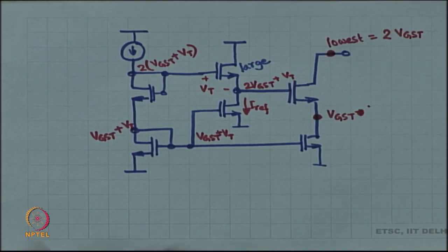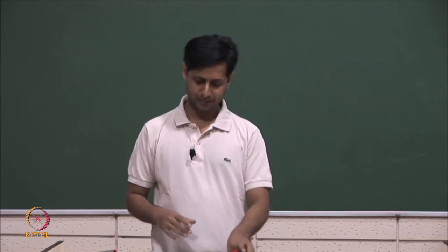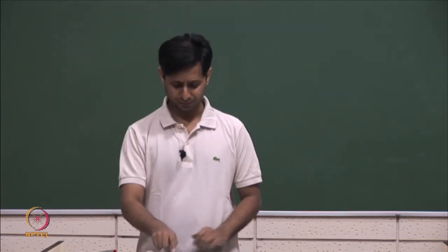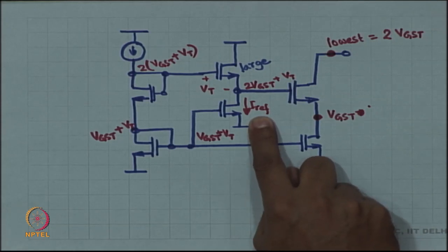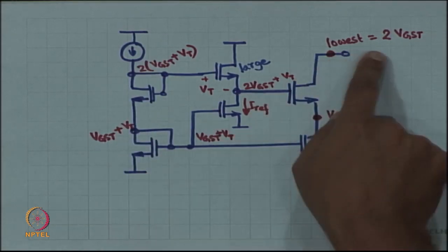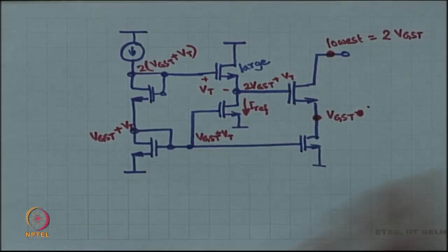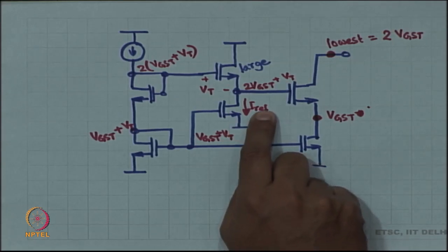Okay. Is this more or less clear, this setup? So, these are all more and more optimized current mirror circuits that you can make. You can design your own current mirror circuit. I mean, you do not have to have Iref over here for that matter, right. Iref means now you have one reference current, another reference current, a third reference current, you are wasting a lot of current. So, make this L very large so that this current is very small.